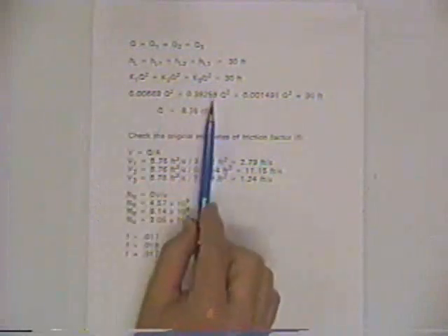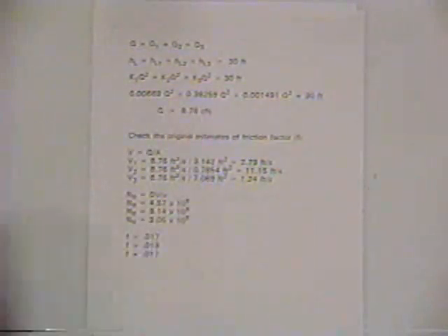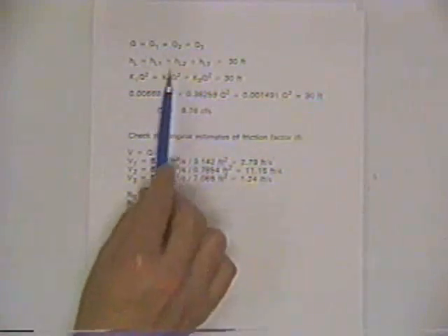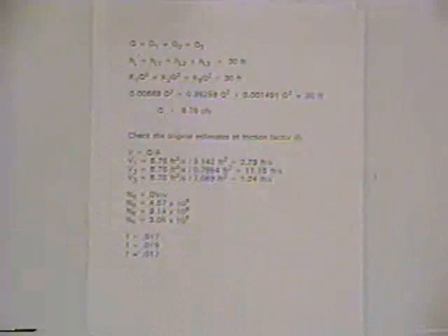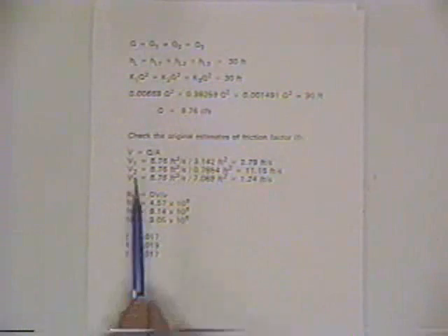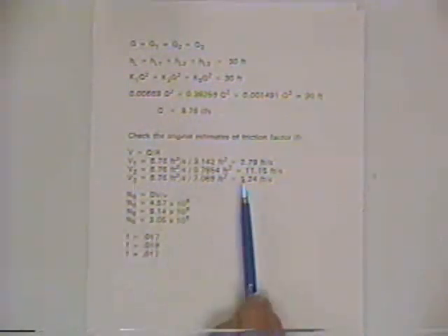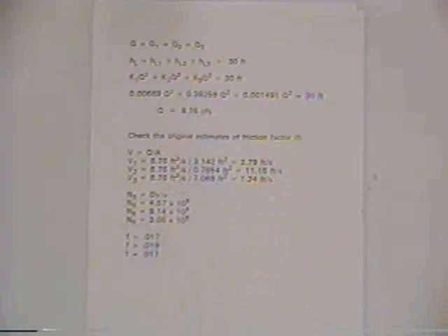On the previous page, we computed the Ks, which means we applied the Darcy-Weisbach equation, and now we compute the Q. It's basically the same problem we had before. We just had to recognize that we're summing the head losses and the Q's are the same in the pipes, which made for a little more computational effort. Once we compute the Q, we can get the velocities, and after we know the velocities, we can compute the Reynolds numbers, and then go back to the Moody diagram to confirm the friction factors. So, same type of problem, we've just got pipes in series added in.